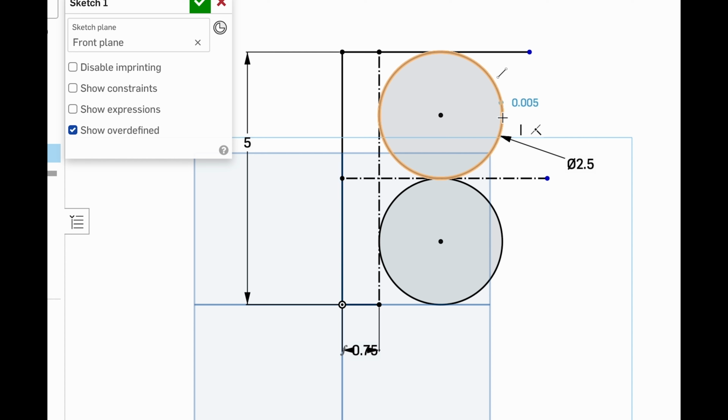And now I'm just drawing even more tangent lines to try and create the outer profile that we see on the actual bumpers. And now I'm just making sure all my lines are going to be tangent to each other. So click on the circle, the line, tangent, and then get rid of all those excess parts by setting the points.